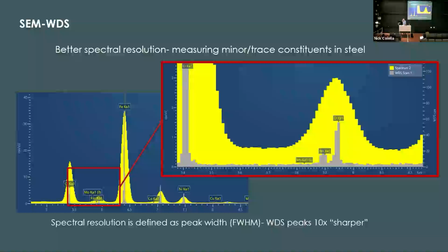The EDS peaks that you see are sort of a histogram of the best guess of the EDS detector at assigning the energy at any one time. The true EDS value is at the peak center. It's just a limitation of the EDS detector design that it can't accurately assign the energy of every single X-ray within that region. If the EDS detector were ideally perfect, it would give you the same plot. It's just not seeing this extra thing that does the filtering.